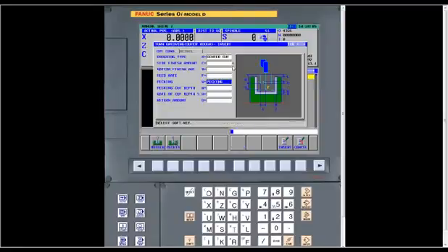A feed rate, a pecking, you can tell it to peck, where it just goes in so far, backs out, for where it will break a chip. This is very handy for grooving because we've all been down that road where we do a grooving cycle and we end up with a chip that's about 3 miles long. We don't want that. This is very powerful. It gives you a choice of where you can get around that.